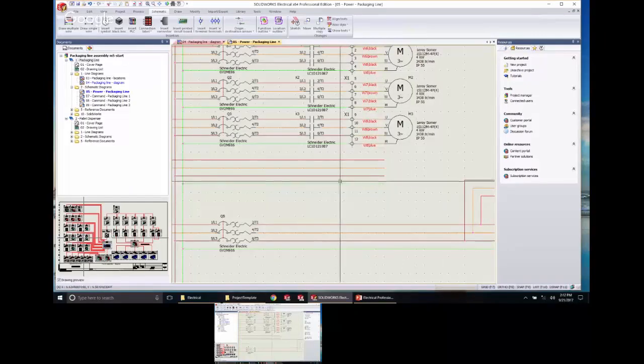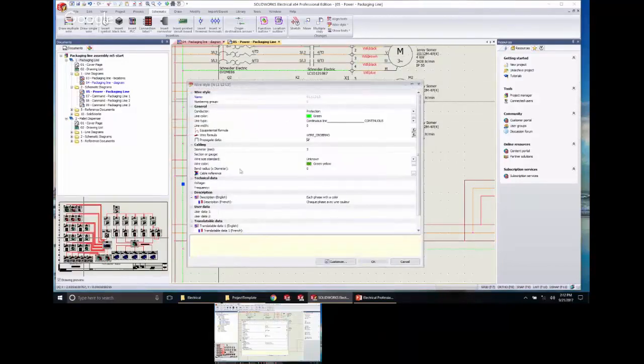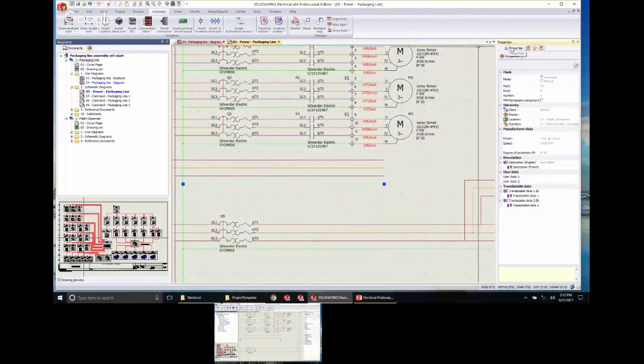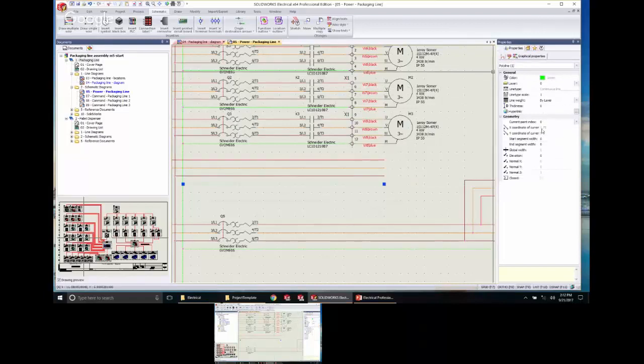The thing is, since this wire was a copy, or the other one was a copy, it's the same wire style, right? I can left click on here, I can right click, everything's right click, right? You can go to wire style, properties, and see what type of wire style it was here. But as I said, I like that they added the properties over here. So now when I have that selected, I can easily see, not the component. There you go. Property. There we go. So I can see that information there easily. Is that properties over there in 16? Yes. Yeah, they made this change in 16.